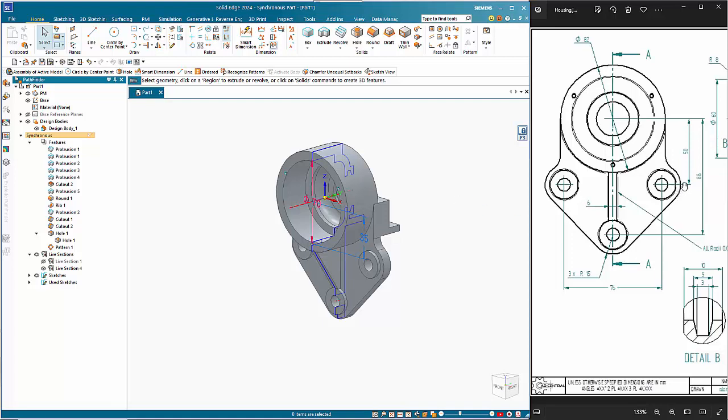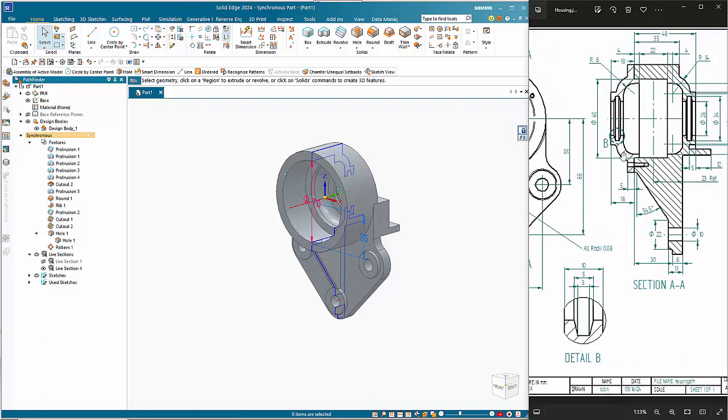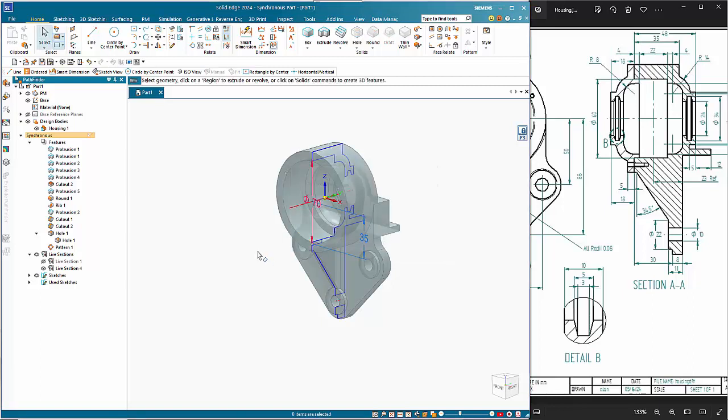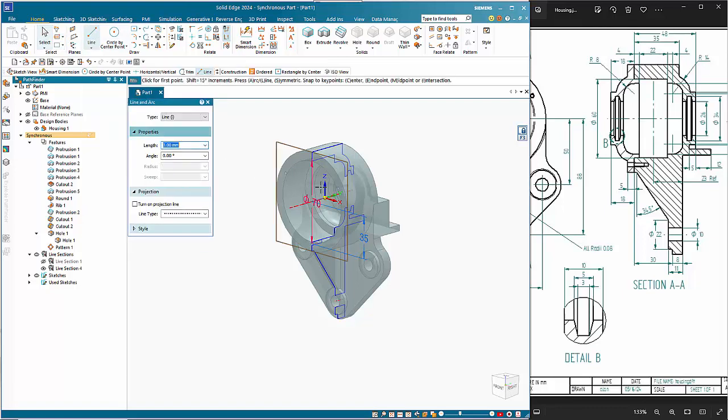And then we want to create the end plate cap, whatever you want to call it. So I could do this as a separate part, or I can do this as a multi-body. So I'm going to just do a multi-body for this. So I'm going to go add body. I'll create the two parts. You've got the option here of a part body or sheet metal body, but I want both parts. So you can see that this is grayed out now, so this is not the active body, but the other one doesn't kick in until I've created my first feature.